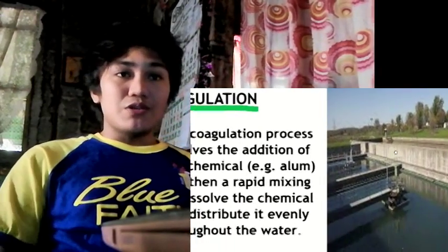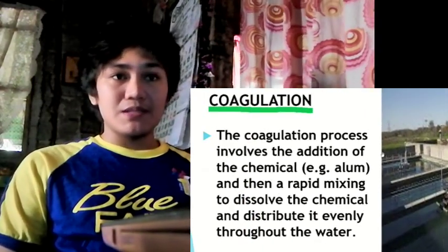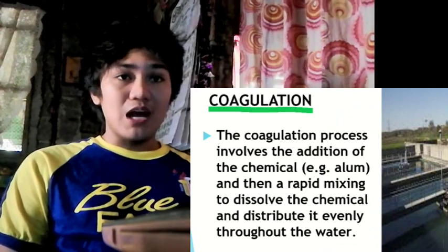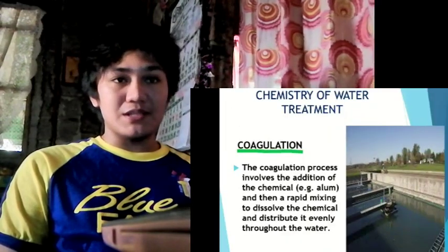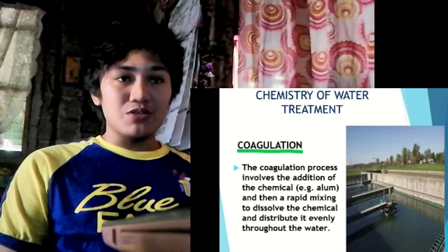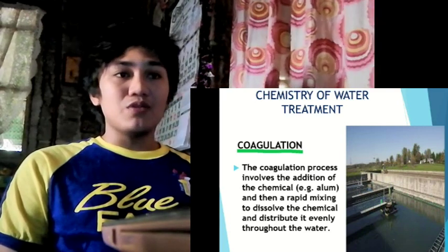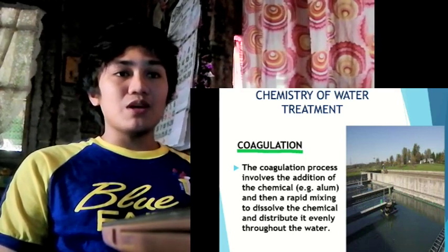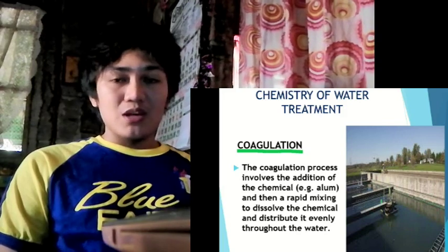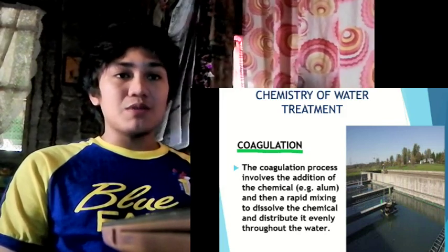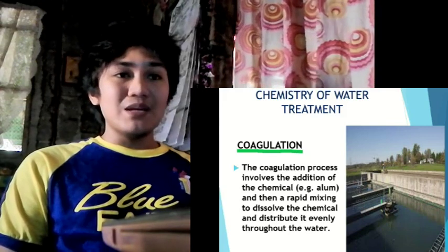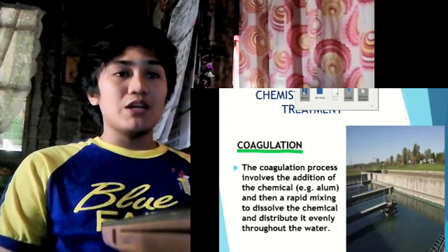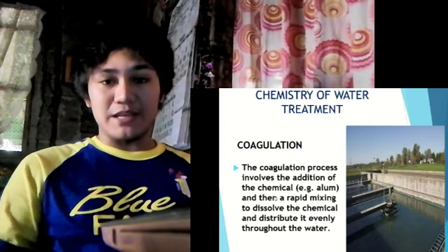The object of coagulation is to turn the small particles of color, turbidity, and bacteria into larger flocs either as precipitates or suspended particles. These flocs are then conditioned so that they will be readily removed in subsequent processes. Technically, coagulation applies to the removal of colloidal particles. Coagulation in this topic or chapter will refer to colloid removal only. We define coagulation as a method to alter the colloids so that they will be able to approach and adhere to each other to form larger floc particles.